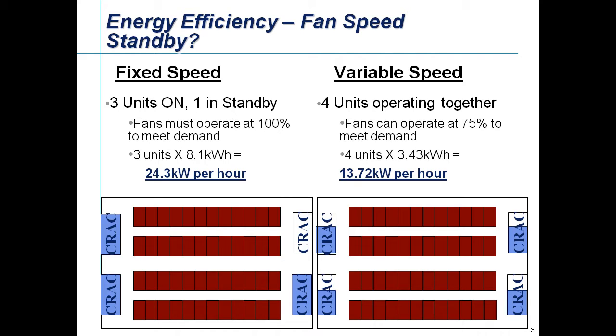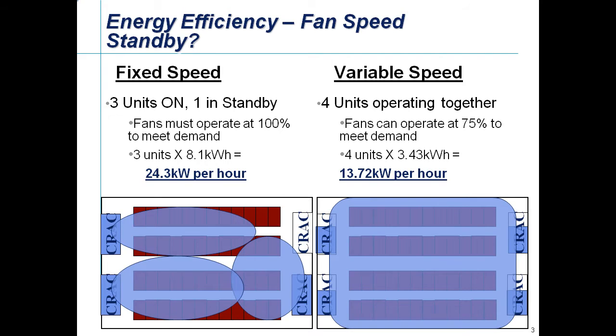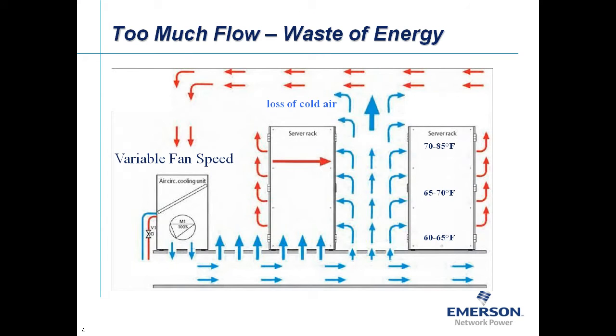In addition to the greater energy savings, the underfloor air distribution would be more consistent with the control strategy on the right. When a unit is placed into standby, as shown on the left, and the fan is deactivated, it creates a void under the floor that the other units will need to compensate for. Depending on the room and unit position, this could create a hot spot in the data center. Add in rotation and you have a real headache.